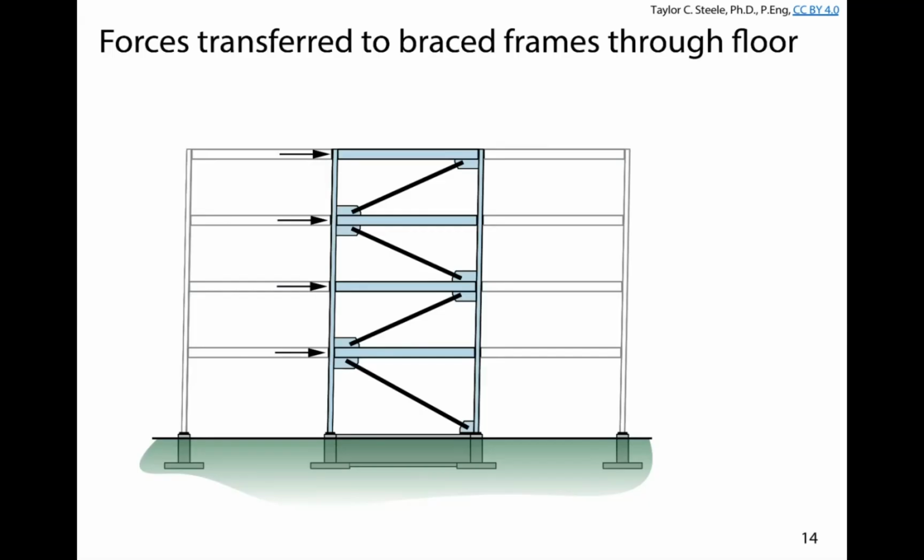And so if there was a symmetric structure with your braced frames at the two ends, this would just be half of that notional lateral force that gets applied at each floor level. Okay, so imaginary forces to generate the same effect of a real phenomenon. The force is imaginary, but the reactions, the resulting internal forces, are not imaginary. Okay, the brace force that develops from this is going to be a real equivalent effect that we develop by applying these imaginary lateral forces.